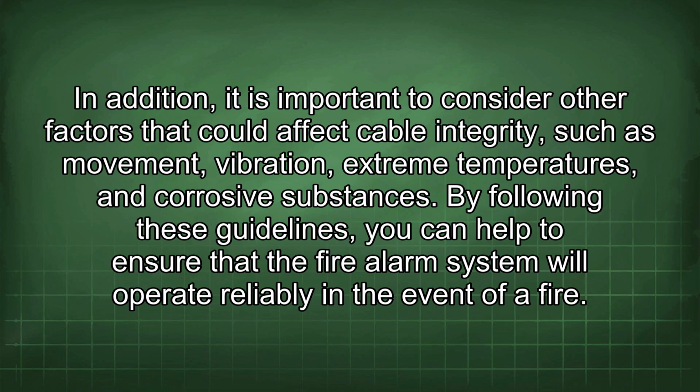In addition, it is important to consider other factors that could affect cable integrity, such as movement, vibration, extreme temperatures, and corrosive substances. By following these guidelines, you can help to ensure that the fire alarm system will operate reliably in the event of a fire.